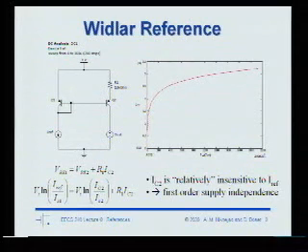If you write the equations, you have that VBE1 is equal to VBE2 plus basically this voltage drop. And if you assume the exponential characteristics for the transistors, you have VT log of current over saturation current. And you end up with basically a transcendental equation. So you actually can't solve this equation in closed form because you have log of I plus I, and you just can't invert that. But of course you could just plot it, right?